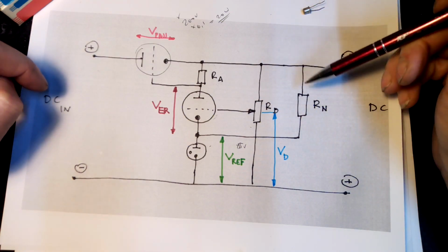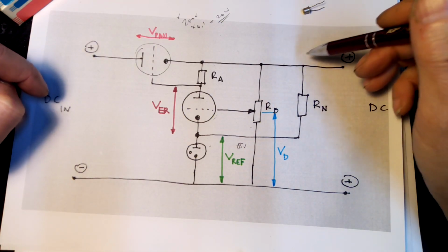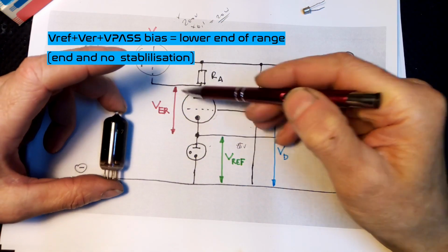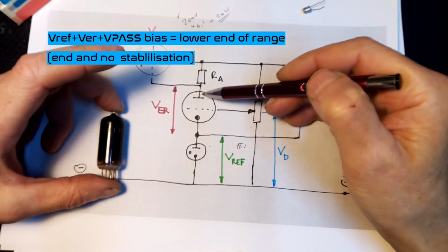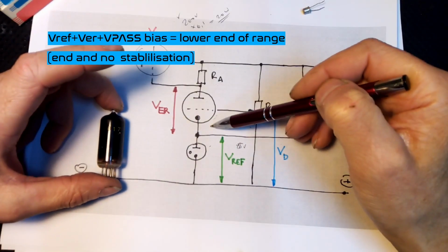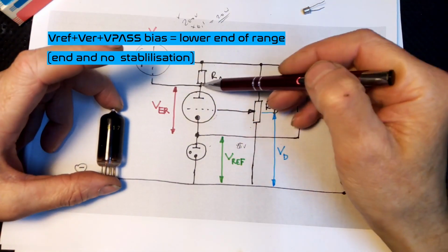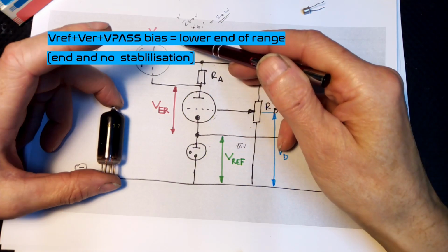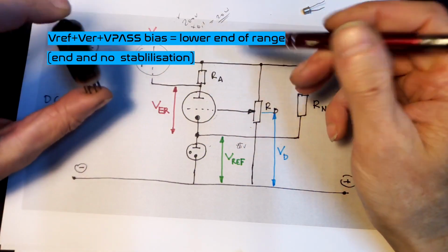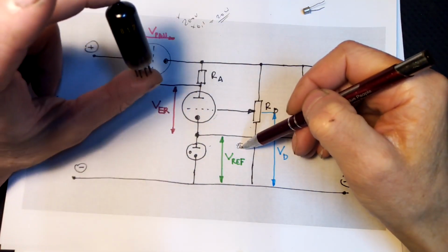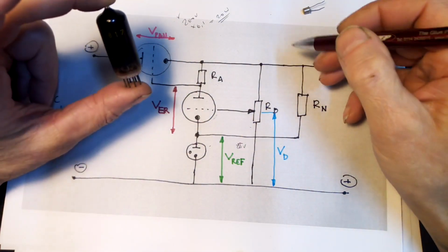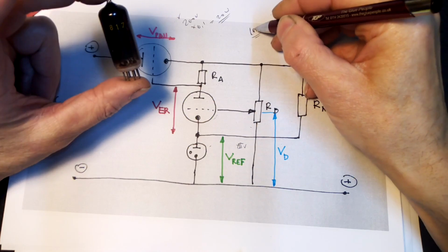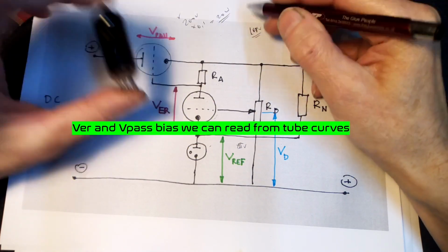Second limitation is a lower adjustment voltage, because we have to consider the voltage reference plus the voltage between anode and cathode of the error amplifier plus the steering voltage. It means a driving voltage, the bias of the grid of the pass valve. So in case of 85 volts from the voltage reference, probably we cannot go down below, I think, 165 volts, if you check the curve, something around that.